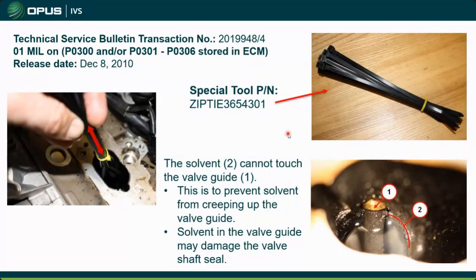But I'm sure most of you are probably familiar with doing decarbs on these. A lot of that carbon buildup issue is due to the crankcase breather system not operating correctly, and or not separating your oil and air well. And that's usually due to a flow issue, because in order for that cyclonic action to work, and for those labyrinths to work, you have to have a good amount of flow through there. And you got to get up to operating temperature in order to really pull that oil out of suspension, and get it to flow back down into the pan and into the engine.